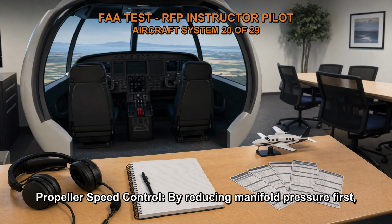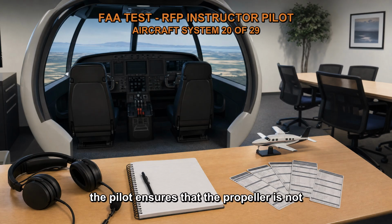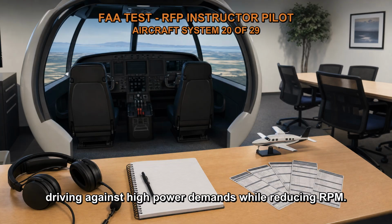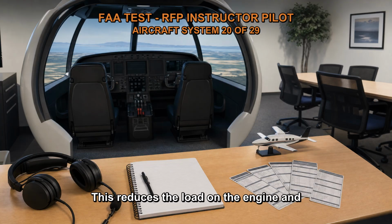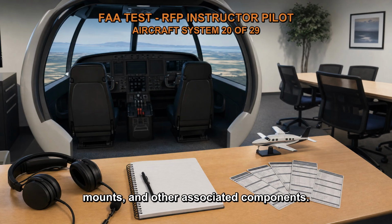Propeller speed control. By reducing manifold pressure first, the pilot ensures that the propeller is not driving against high power demands while reducing RPM. This reduces the load on the engine and minimizes the stress on the propeller blades, engine mounts, and other associated components.